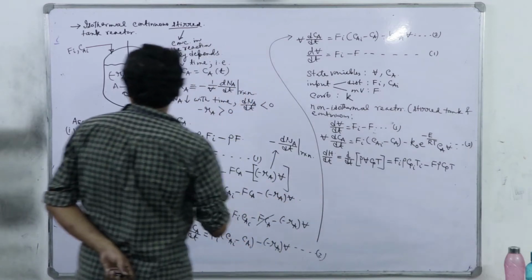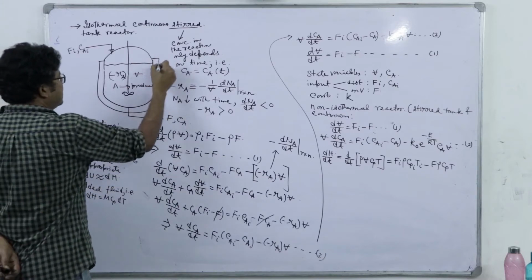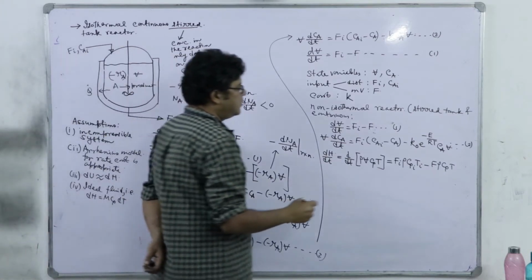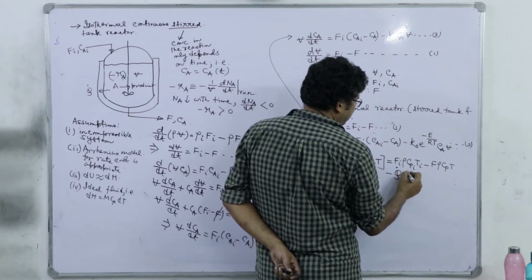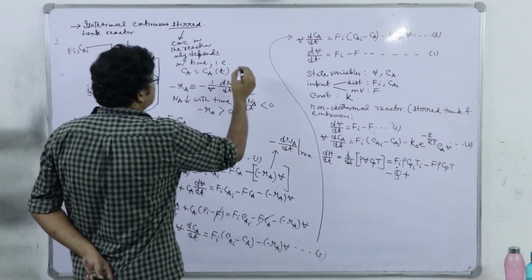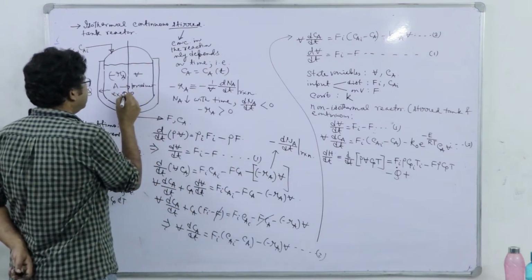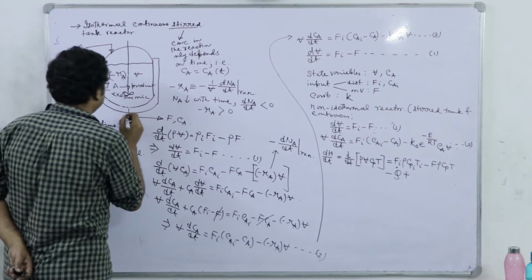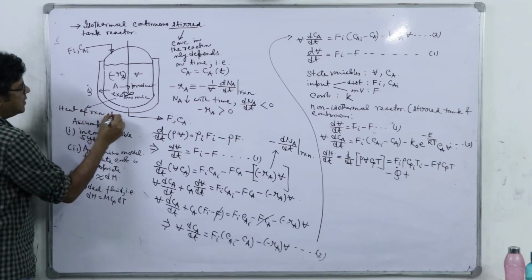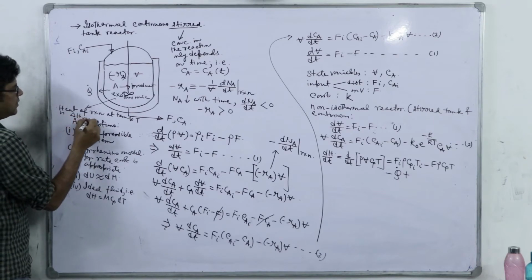Next, we have a jacket, let us say it is an exothermic reaction, and we are removing heat continuously at a rate of q dot. So, minus q dot plus there will be heat generation, right. Say the heat of reaction, as it is exothermic, say the heat of reaction at temperature T is delta H Rx, right.